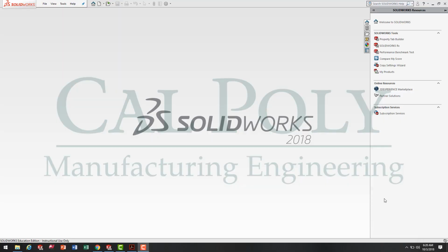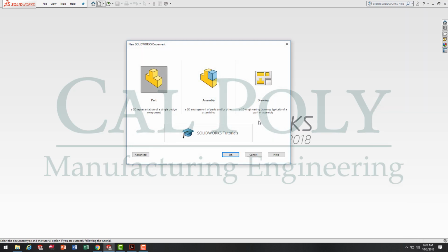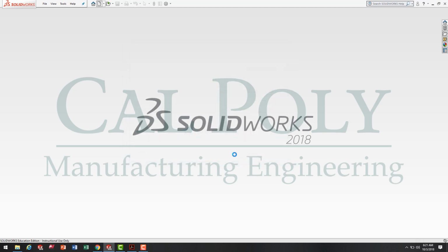In this video, I'm going to show you how to draw Lathe Project Number 1's engineering drawing. So open up SolidWorks and go to File, New. If you haven't created the solid model at this point, please go back and watch the video on how to create Lathe Project Number 1 solid model before creating the drawing. Now, once you have a solid model created, we're going to click on Drawing and OK.